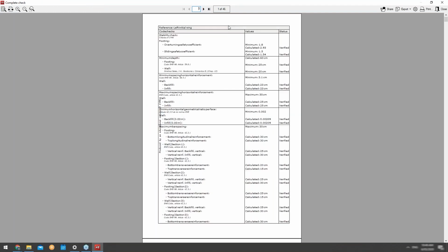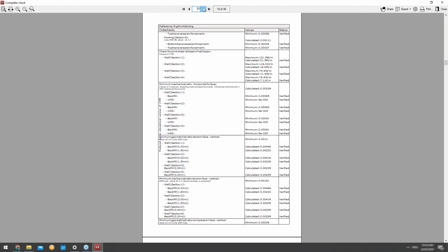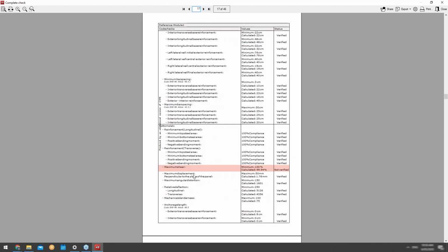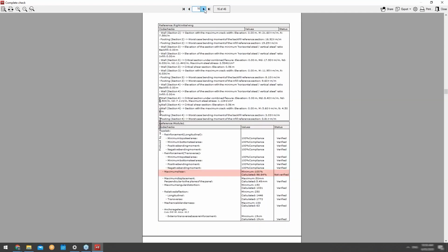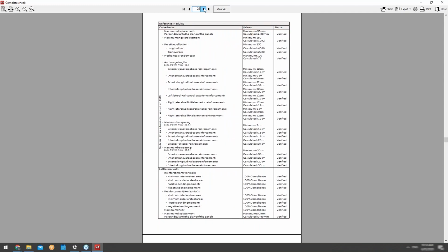So now this is a full report on the box culvert here. Starting off with the left initial wing wall and then progressing forward. And you can see all the different types of checks that have been defined. You can see the maximum shear, which basically is negligible, and also another negligible value here. So that's basically the sort of compliance checks that we can do and design capabilities we can define within the program after everything has been defined. I can, of course, share, export, print all these reports in one place, etc. And be able to share those basically with ease at a click of a button.